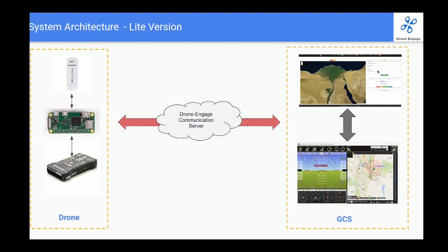And this web client can transmit data locally to Mission Planner or Ground Control via a plugin called Android Web Plugin. Android Web Plugin is simply a command line that you can run, and from the web you can activate the telemetry and you will find that Mission Planner is connected directly to the Pixhawk via this system.